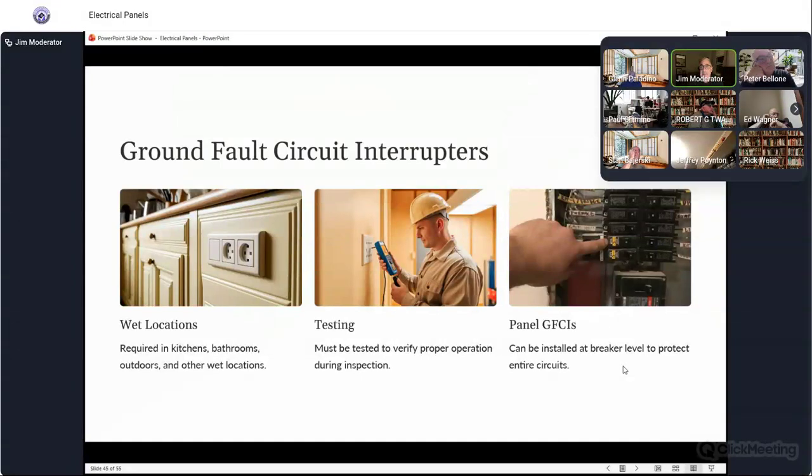They didn't even want to go into the basement for the inspection because they couldn't walk down the stairs. I said, you need GFIs. And the husband said, I will just put a GFI breaker, because he knew stuff. And I said, you're not going to do that. Why? Because there's no way for you to go down and reset it. You're going to have to change all the breakers in the kitchen so that they can be reset at the outlet. So that's important. For younger people, I'll tell them it's probably easier and better. The breakers last longer. They're just as reliable, but you're going to have to walk to reset it if it does trip.